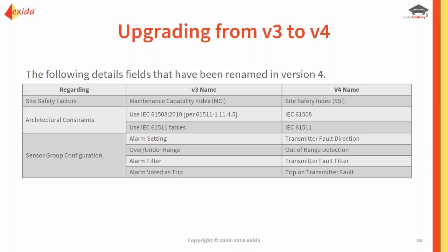So if you decide initially that, let's say 2 out of 3 voting, the 3 transmitters go to 3 separate analog input modules, there is voting over those analog input modules. If you decide that the 3 channels go to 1 single input module, then there's no voting over the analog modules themselves, only over the channel. So the analog input module becomes a common failure to all 3 inputs. So that will change your calculated P of the average.